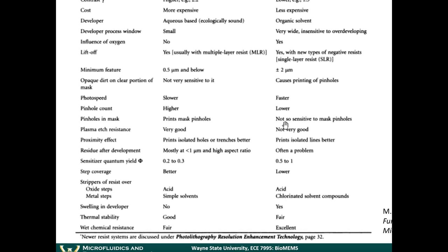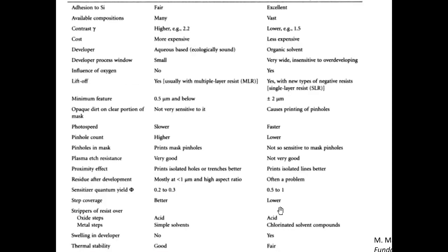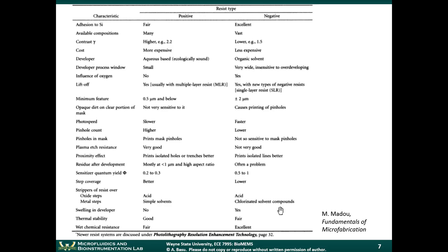One thing you do have to be careful about in negative photoresist is the swelling. If you keep even a negative resist in developer for too long, the photoresist patterns will actually swell, and when they swell, they can come off the wafer. Okay, so these are little things that you have to be careful about. From a purely theoretical standpoint, none of these will really matter that much or make that much sense to you until you actually go in the clean room and make your device. And just doing one photolithography step is taking you weeks because these little details are driving you crazy.